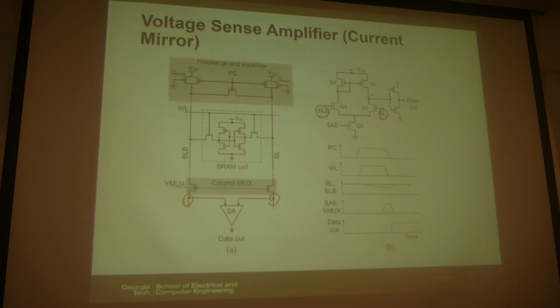So what you can do here is to replace this part with a latch. So basically those two nodes can be those two nodes. So still here you have the voltage input through the differential pair, and then the pull down strength for those two nodes will be different. But this latch-based one will flip faster than this current mirror one, because positive feedback is built into the latch. So if you have any voltage difference here, then it will quickly flip.